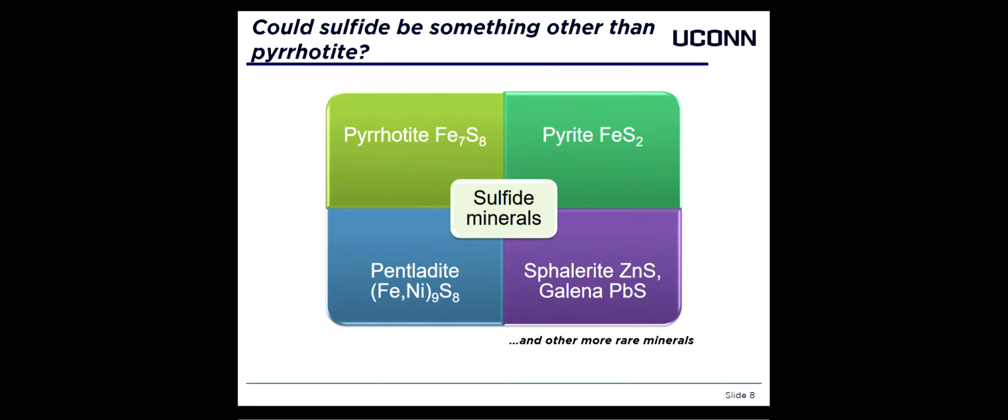It is important to know that our method does not yield direct information on whether sulfide is present in pyrrhotite or not. Our method essentially captures all mineral forms of sulfide, some of which are shown in this diagram. All these forms participate in similar reactions and are harmful to concrete, so knowing their total concentration provides a better idea of the reaction potential.